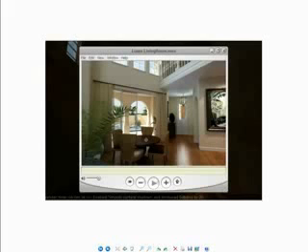Even if an object like a chair is just a few inches away from the window or door opening, but it's so close that it actually occupies the same space as the light, I would still want to place the light just outside, because you can easily have an unrealistic hotspot appear on your objects that are very close to the light. But with the exception of objects that are just in front of the window or door opening, I will always want to place the light just inside.